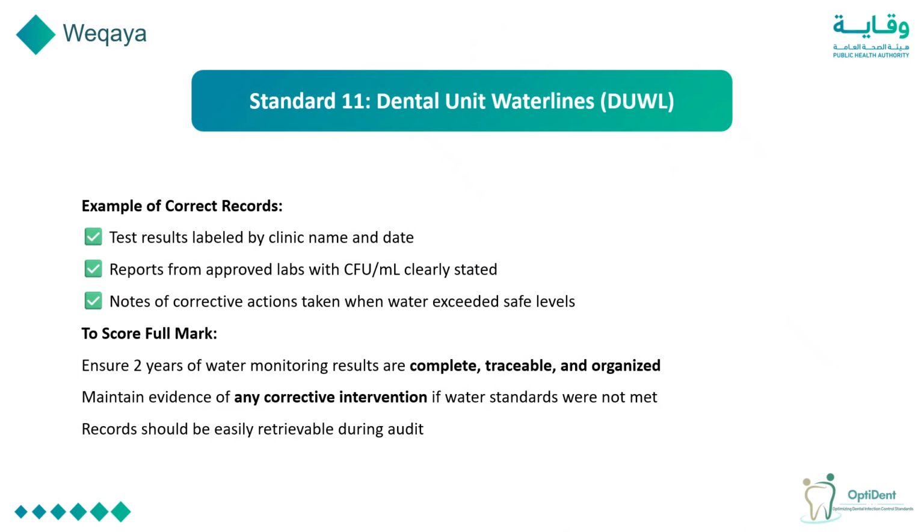I will mention some examples of correct records, like the test result labeled by clinic name and date, reports from approved labs with CFU per milliliter clearly stated, and notes of corrective actions taken when water exceeds safe levels.